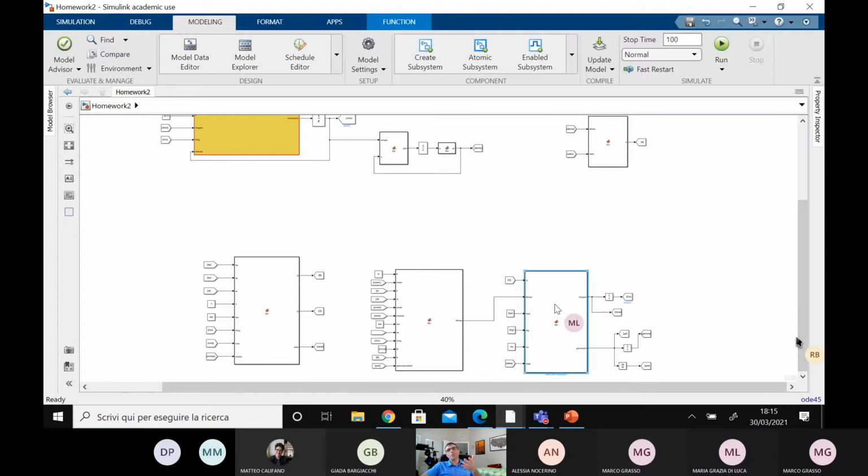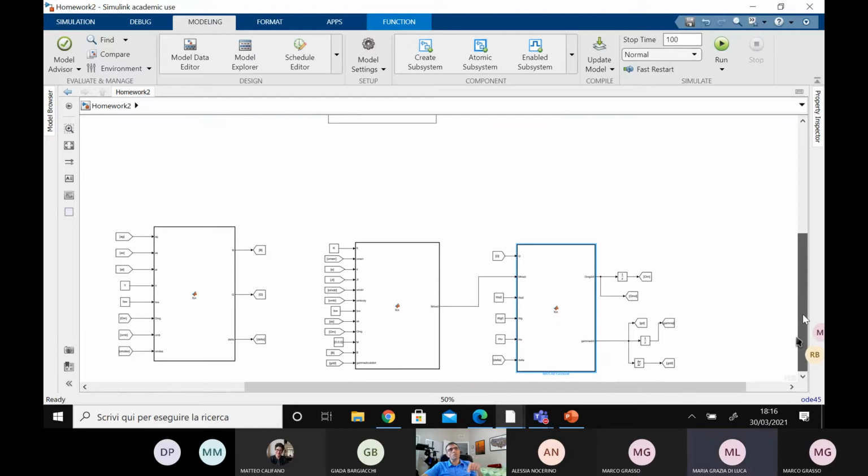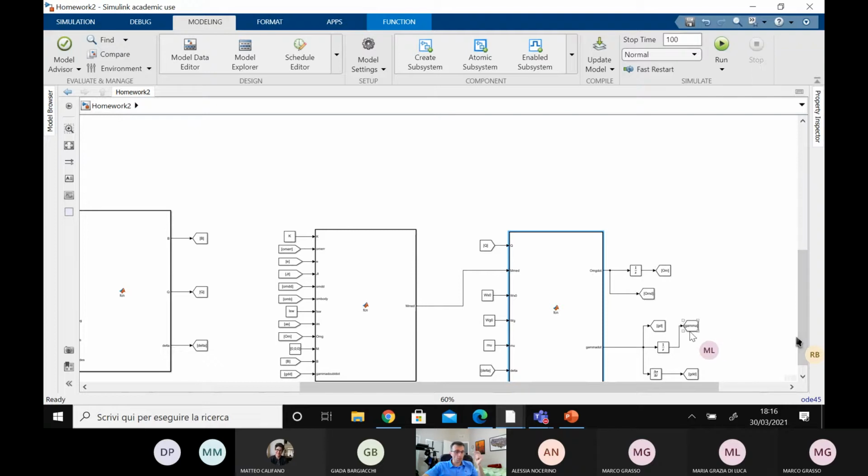and you can choose, because that's your controller, right? So eta is your control variable. It's the gamma dots and the omega dots. You can choose that they start all at 0 or something else. It's up to you. It's the initial condition for the control variables, the gimbal rates and the acceleration of the wheels. And I would say we can start at 0. It's a reasonable assumption. And so if you broke it in 2 pieces before, you can put 2 memory blocks, one in front of the omega dot coming out and one right after the gamma dot coming out.